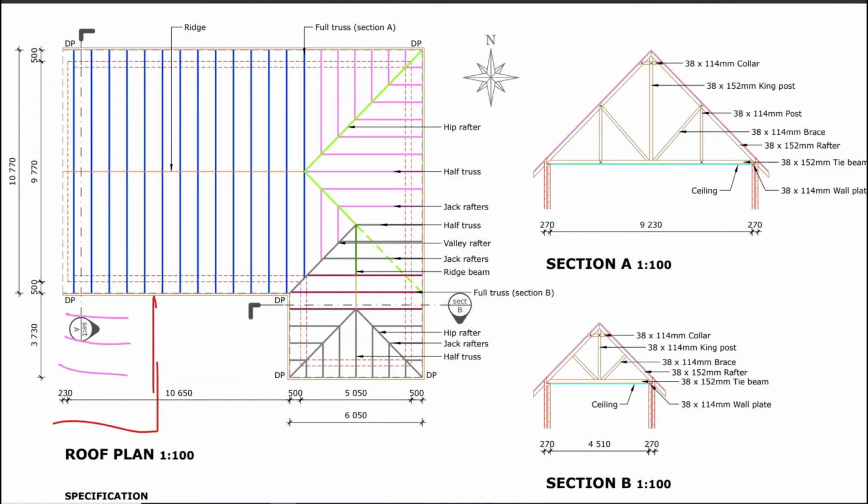What you'll do then is you would take this rise over run rule, you'd split up this typical rafter length, divide it, and then multiply by how many units down, because 2 units down will mean 2 units to the left. So that's how you would find values elsewhere that might not have enough information for you, and you transfer it across.